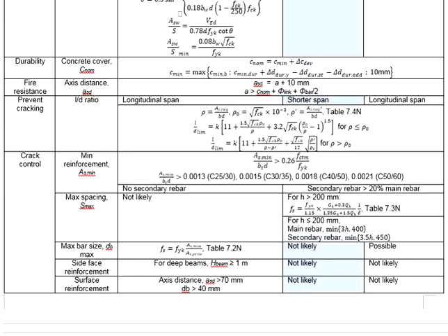Why is it so? It is because the slab is likely to bend in the shorter span as compared to the longer span. Therefore, there is no point for you to check the L per D ratio for the longer span of the slab. There are quite a number of ways to control cracking. One of them is by the As,min. For the As,min, you need to check two aspects.